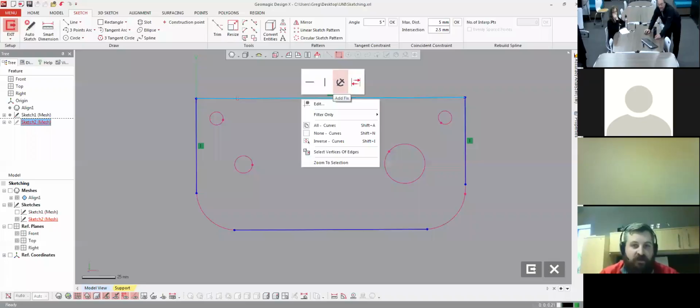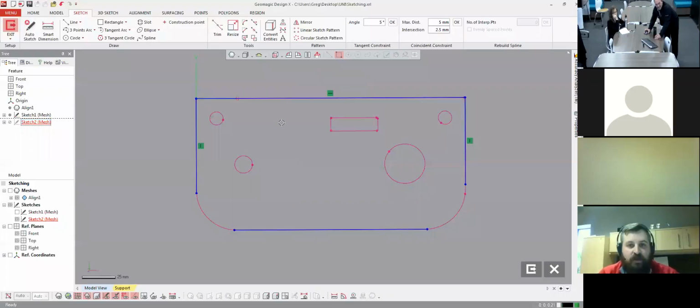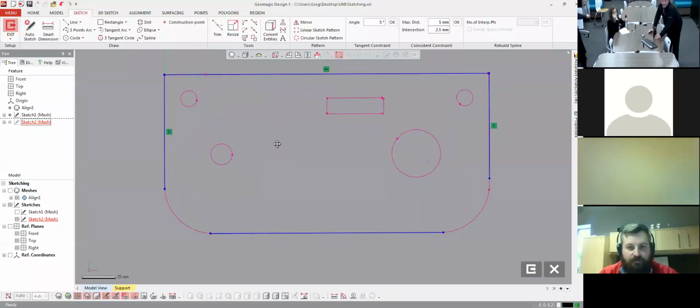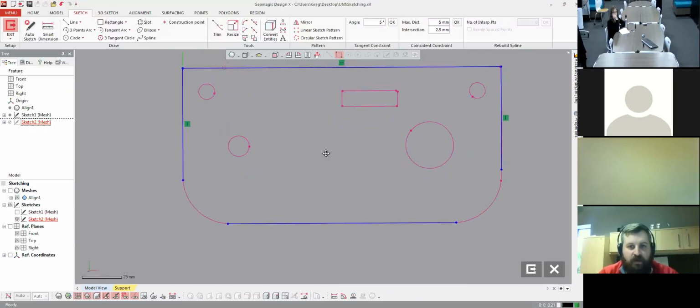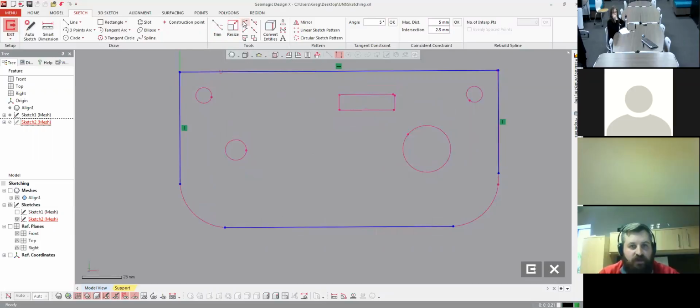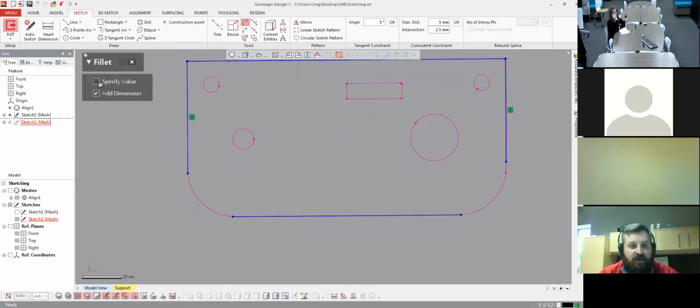Value, so I don't have to add any dimensional constraints. We'll lock that line into the appropriate area, but for now we'll leave that. So next thing is we're going to fill in these radii. So there's a radius function. It's buried in the Tools command. It's called fillet.